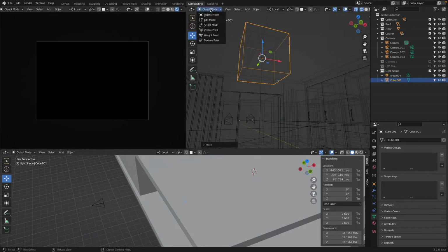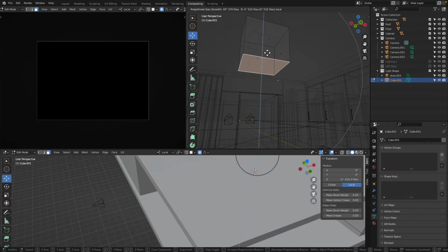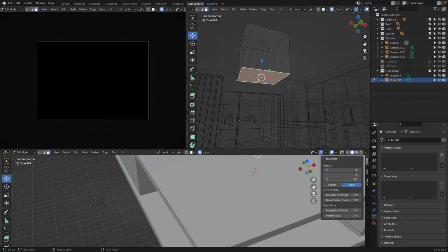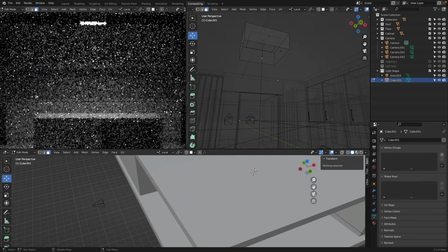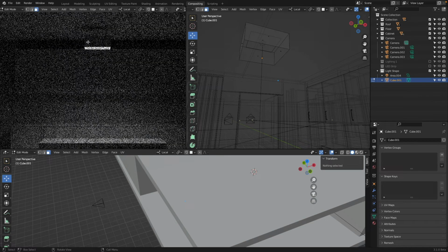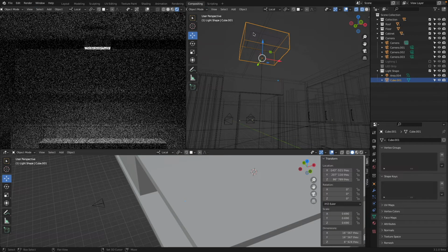And I will go into edit mode, face select, select the lower face, move this one. Oh, we have to press O or turn this off. This is on to there, X, and then we delete this face. So we open it. And look at that. We have a nice light fixture. It's an amazingly boring looking cube with an area light inside.